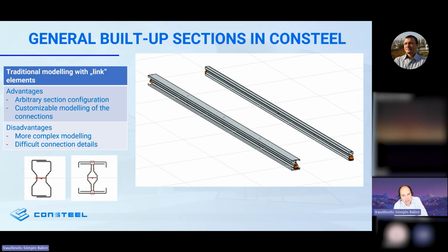And then at the locations where the real structure has physical connections, the engineer could define link elements or rigid bodies or virtual beam elements. On these virtual beam elements or links or rigid links, any sort of releases could be positioned. So basically, the structure could be modeled very closely to reality, but it was not very easy.